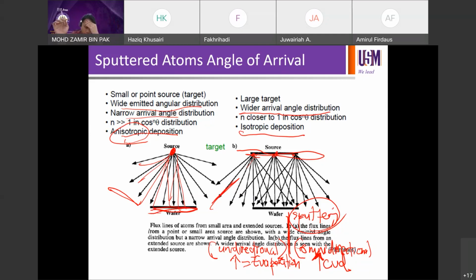center to edge. Because when you run sputtering or evaporation or CVD, it comes with characterization, right? Remember, processing is followed by characterization. If you sputter onto a silicon wafer, for example, you want to know what the thickness is in the center and what the thickness is on the edge. So maybe you have a couple of points during your characterization, and you might want to know all these points for your thickness uniformity.